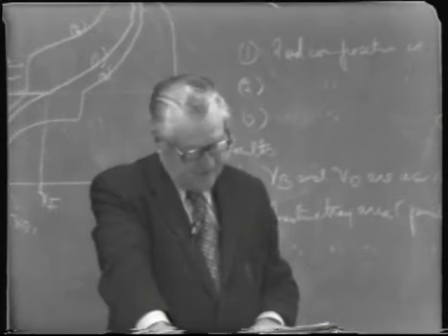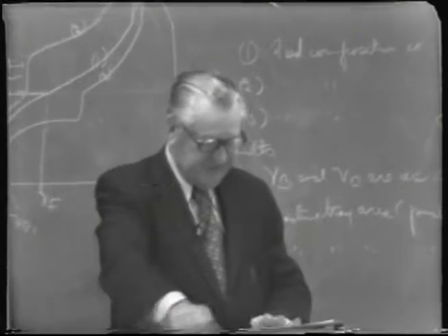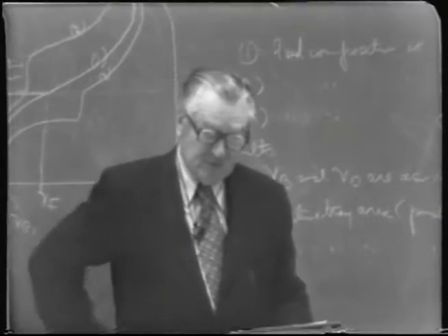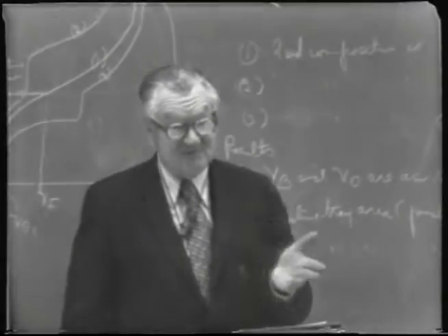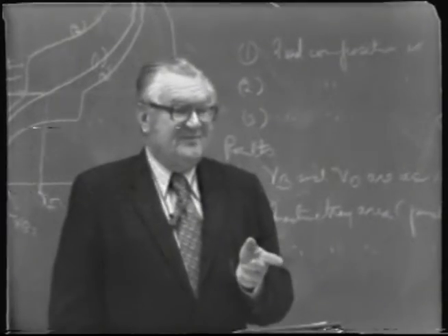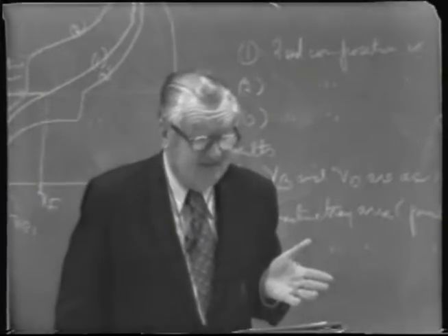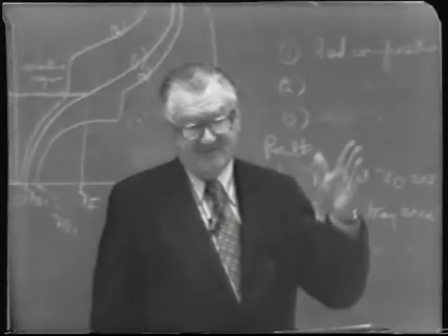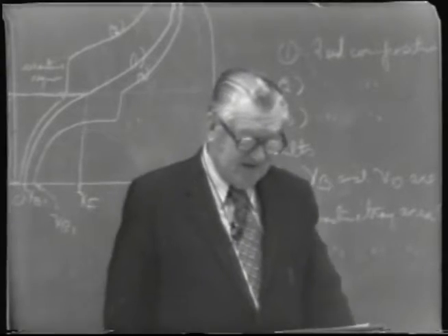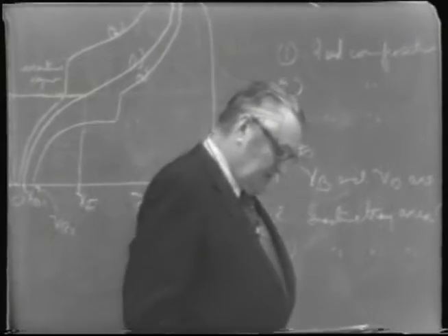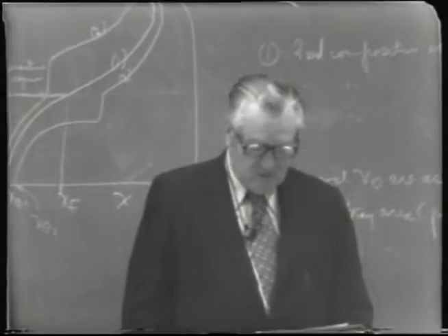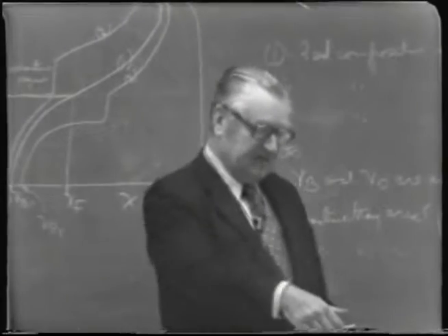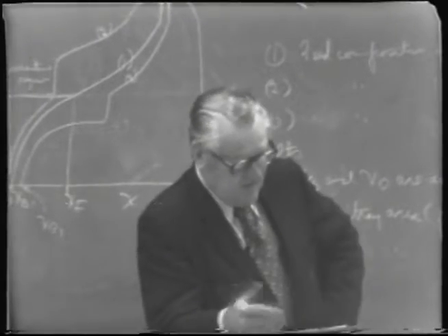So if you apply those to a production of beverage brandy, in which the distillate concentration is only 85% by volume, and which, as the examples we've had, I think, indicate, you only take 2 or 3 ideal stages, or 4 at the most, to reach this concentration. The rest of the trays, even allowing for a reasonable plate inefficiency, are considerably more than required. Now, what I've just stated is from the viewpoint of concentrating alcohol.